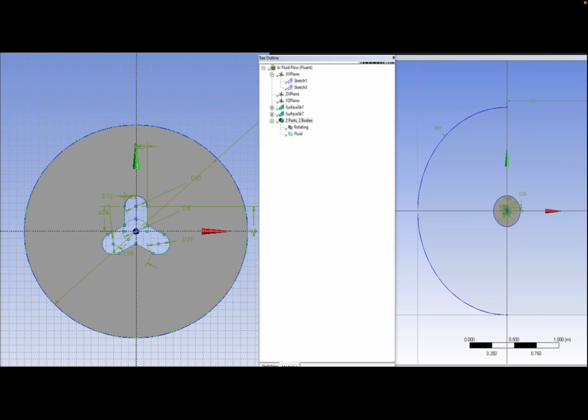You'll do the surface by sketch on your fidget spinner first, and then you'll do a surface by sketch on the circle, and do a boolean and subtract the fidget spinner from the circle in order to separate the two features. Next, you want to do a new sketch on the same plane to make your airfoil.